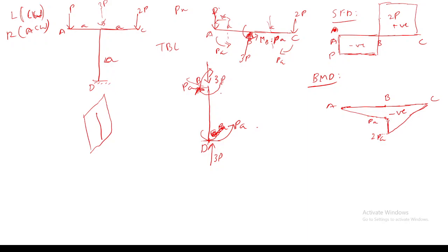Okay, so here, can you say in which plane this PA is actually acting? Whether it is in the right hand side plane or in some other plane. From which plane is this PA actually visible? This is wrong. Front. What I have told is wrong. Front, yeah, in the front plane only this PA will be visible, right?